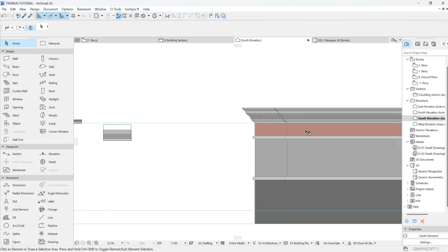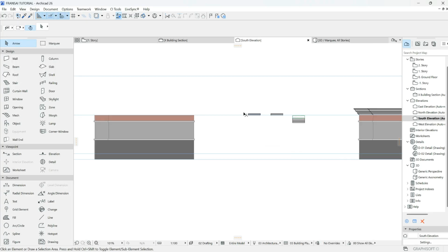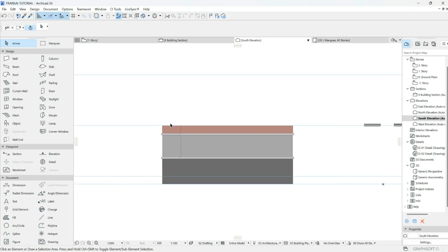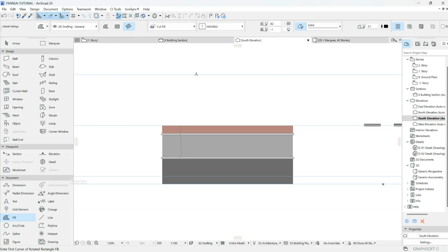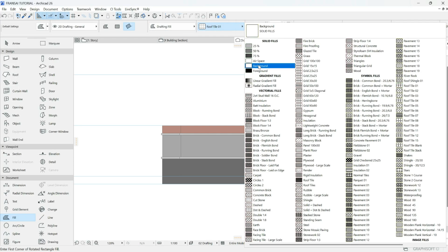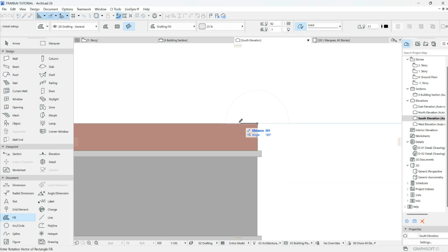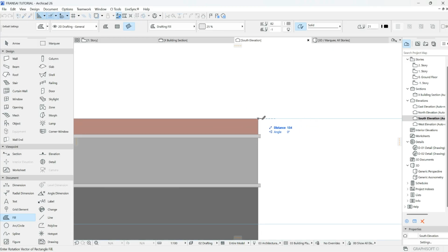Okay, now this is what we have on our elevation, our concrete fascia workplace. This is the elevation, this is the other ones we just used. So now I want the ones with straight one without curve. So let me pick on the fill tool, pick on this. Let me, although this is not necessary, just pick on the fill tool. So this is my fill tool. I also want the distance from the wall out to be 450. Or let me say 600. No, let's work with 450. 450, enter. Okay.